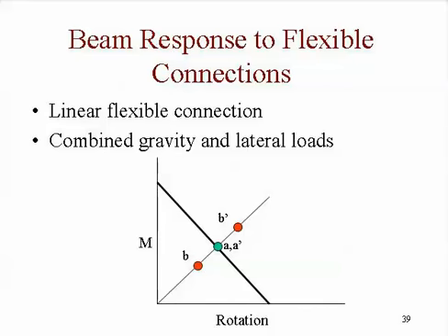And so you start out with two parallel columns and it moves sideways, all right? And this connection on that side opens up. The gravity load made it close up. The lateral load made it open up, so that one the moment in the connection is reduced. That's point B. And on the other end, the moment or the displacement due to the lateral load and due to the gravity load are going in the same direction, and so that moves us out here to point B.